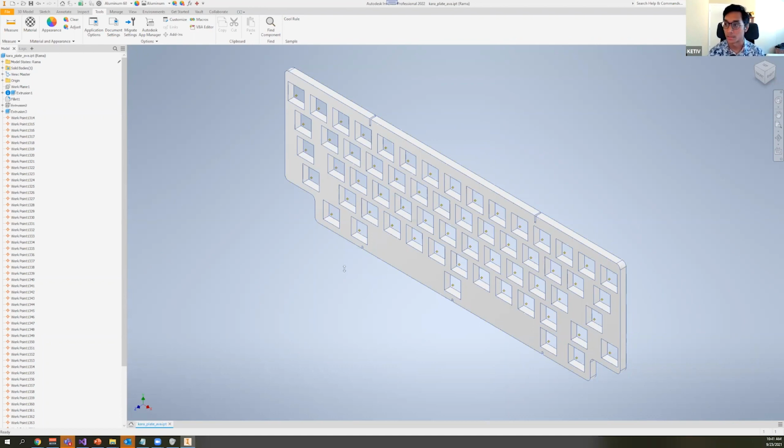So if you want to constrain face to face, you obviously have to check for two faces. You have to make sure that they're not constrained against each other and stuff like that. And that just becomes an extra headache to balance the extra needs of the constraint functions versus just a single line of, I'm going to ground it at this exact position and this exact orientation, right? And so the same thing could be said outside of automation too, where grounding is sometimes a good option because it's simpler in general. Yep, just simplifying because we don't need the additional information.